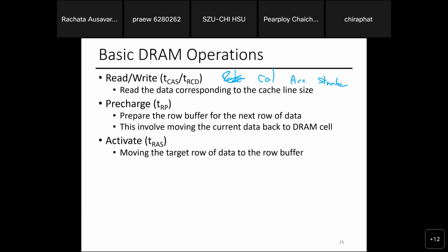The thing is, when you put in a row, each piece of data is what we call a column of data. That's why reading is going to the column and reading that. Column access. Row pre-charge. Row access strobe. I'm not going to ask you what they stand for. The reason I put it in is because when you read the DRAM specification, they'll have the numbers, and now you know how fast the DRAM that you're buying is.